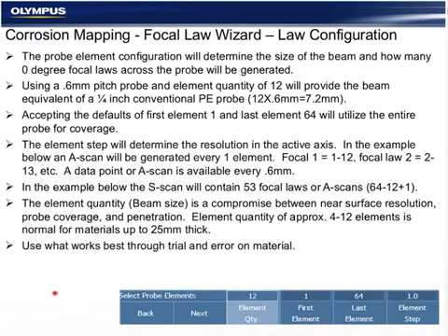The focal laws are entered directly into the calculator, either through the NDT setup builder that we'll see in a minute, or in the OmniScan user interface. We're going to see a graphic that explains this, but the element quantity is directly relevant to the size of the probe. In conventional UT, we call that diameter or size.